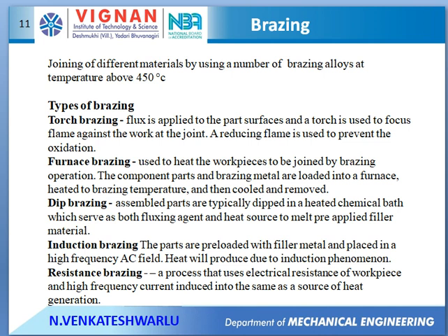So we can focus the beam, and the area of the weld can be reduced. The beam is focused on this limited area, and we can reduce the heat affected zone compared to gas welding as well as arc welding. In comparison between arc welding and gas welding, the heat affected zone of gas welding is more than that of arc welding. This is about the heat affected zone.